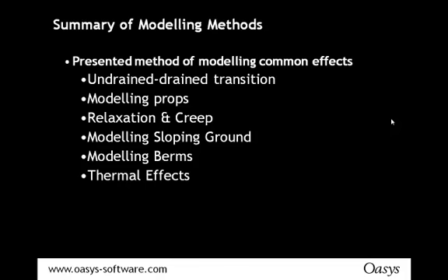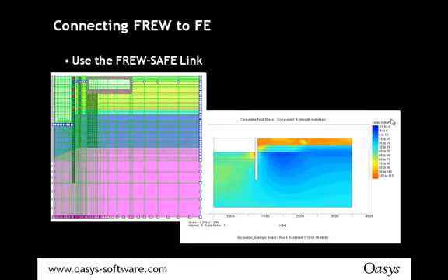And I'm now going to move on, as I previously suggested, to what would happen if all this wasn't maybe adequate. Maybe you needed to do a seepage analysis. Maybe you want to have a look at the settlement profile nearby, or have a look at the impact of your retaining wall on a tunnel, or look at the impact of a newly constructed tunnel on your retaining wall. So what would you do with all these things? You would probably consider using something like 2D FE analysis.